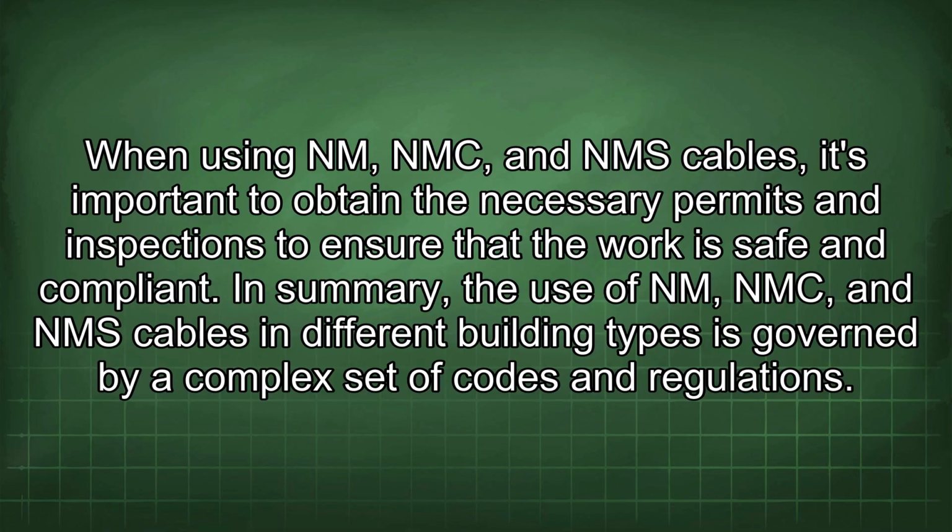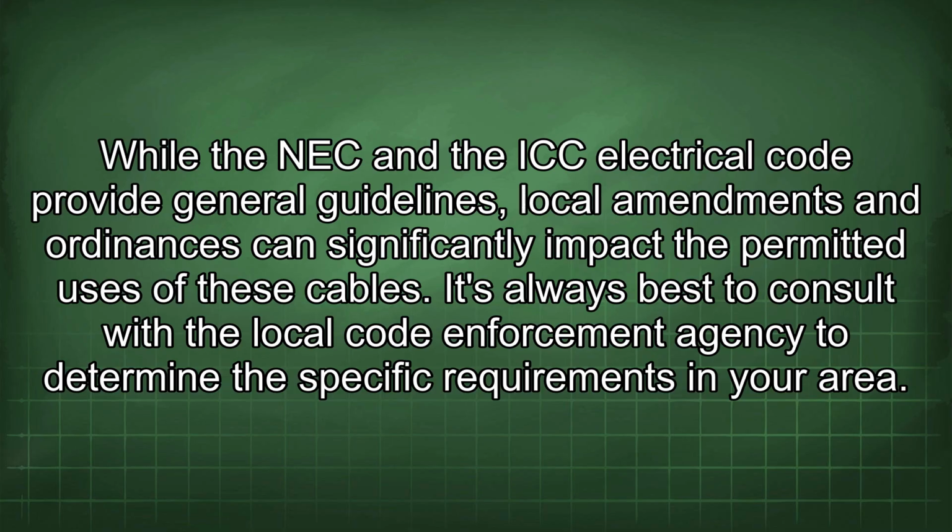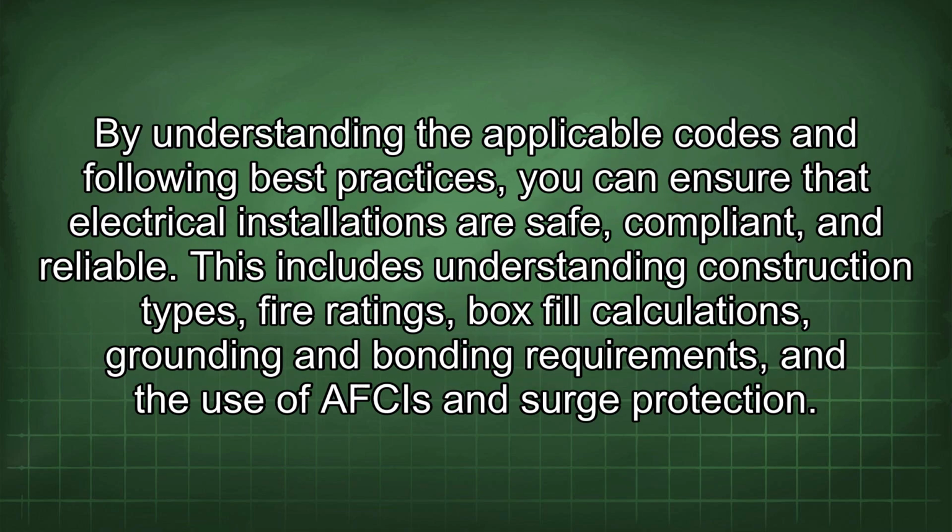In summary, the use of NM, NMC, and NMS cables in different building types is governed by a complex set of codes and regulations. While the NEC and the ICC electrical code provide general guidelines, local amendments and ordinances can significantly impact the permitted uses of these cables. It's always best to consult with the local code enforcement agency to determine the specific requirements in your area. By understanding the applicable codes and following best practices, you can ensure that electrical installations are safe, compliant, and reliable.